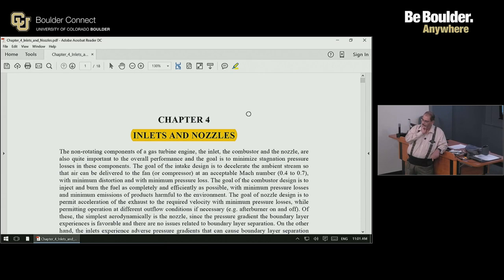The problem Pratt & Whitney is having with the A320 engines is that after the engine has been operating for some time, if they shut down the engine, or after landing, then the lower parts cool quickly, but the upper parts of the engine don't cool that quickly.